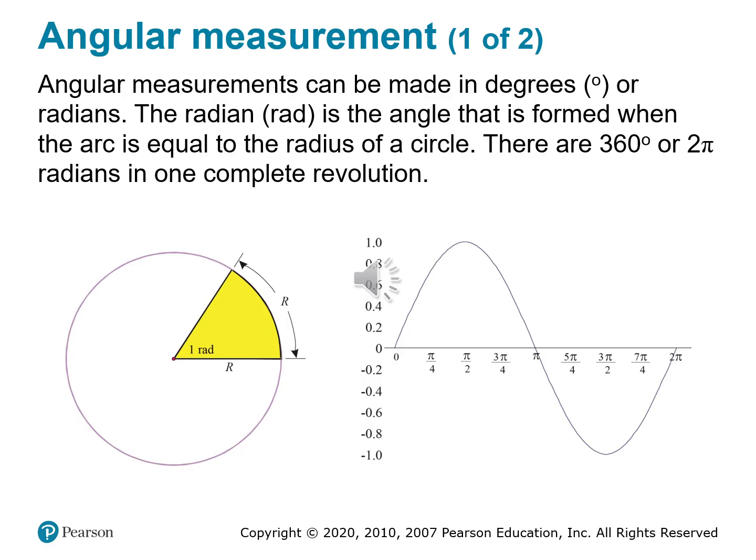Because when we analyze sine waves mathematically, especially in electronics and in signal processing, we often express the waveform's position in terms of radians, not seconds. On the sine wave graph, the horizontal axis uses radians, so 0 to 2 pi equals 1 full cycle. Pi is half of that, which is 180 degrees. Pi over 2 is the peak. 3 pi over 2 is the negative peak.